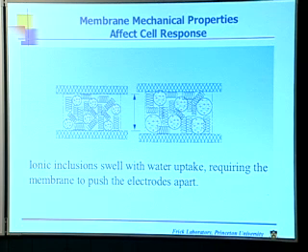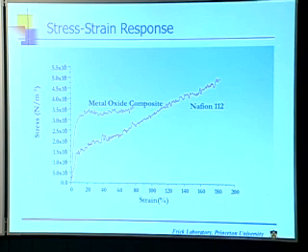So it doesn't have to do with evaporation. It has to do with the Nafion. And if you're a big fan of stress-strain curves, you can see this effect pretty nicely right here. If I have any chemical engineers in the class, I don't know, right? If I take a pure piece of Nafion and I carry out a stress-strain curve, this is what I get. I get an elastic region here, and then I get an irreversible deformation above this level.